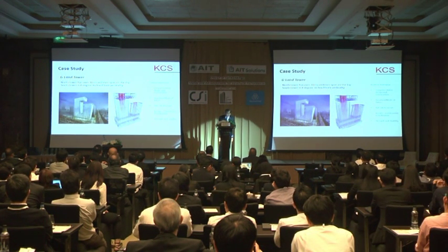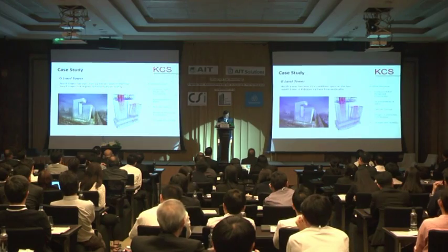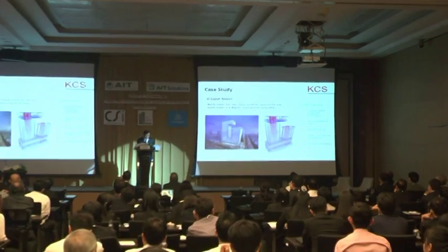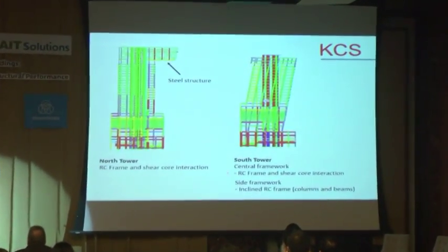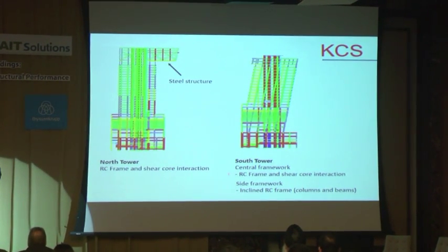This building requires extensive and advanced precision of structural analysis to ensure stability, unlike the Leaning Tower of Pisa. For the 31-meter cantilever at 147 meters above ground, design and construction coordination is vital. Construction technique dominated the design.